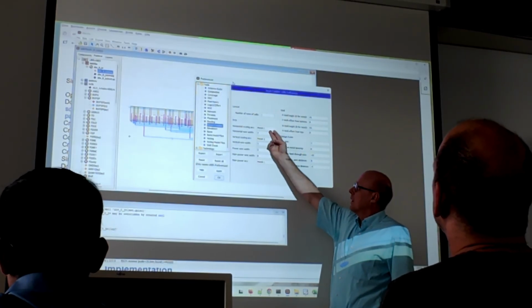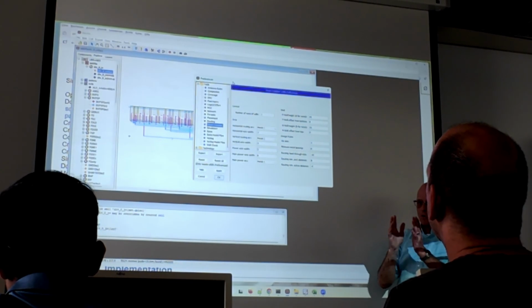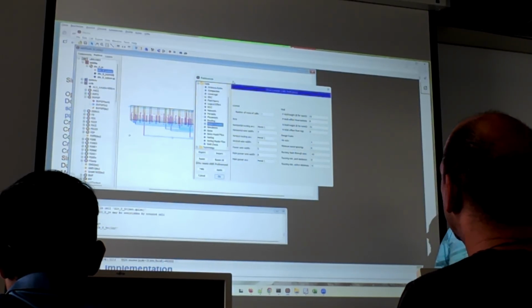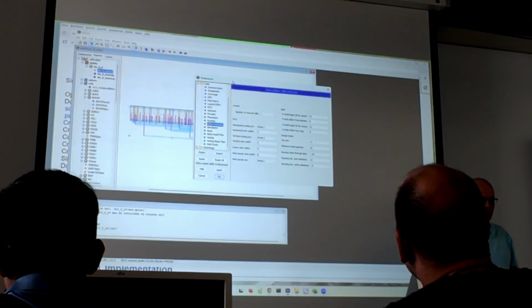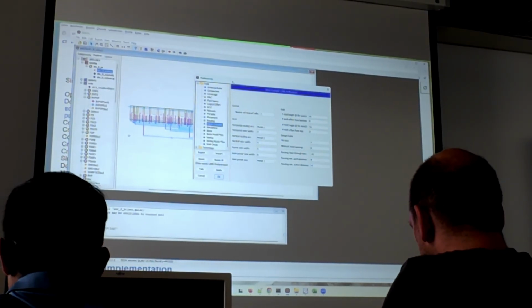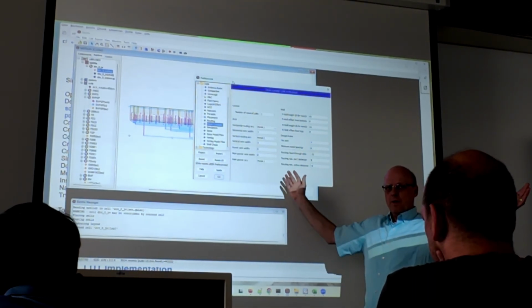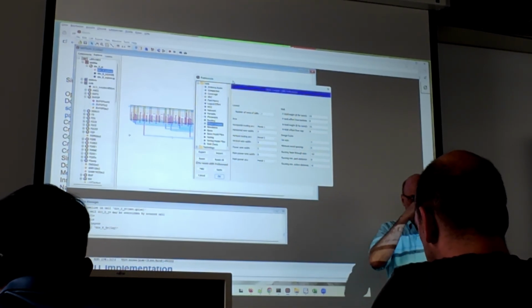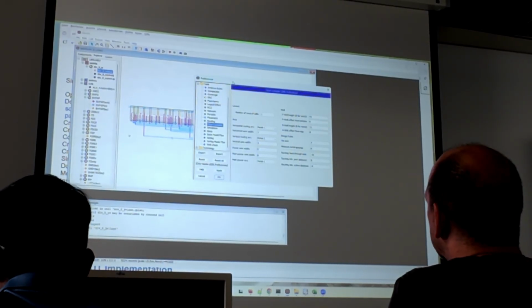You have here the metal 1, 4, metal 2, 4, and then the spacing of the cells to get them as close together as possible. You have the -32, the 8, and the -9 here. And then you get a very dense layout. If you have other numbers here, some positive, all the cells will be placed further apart, so you will not get the minimum size of the layout.